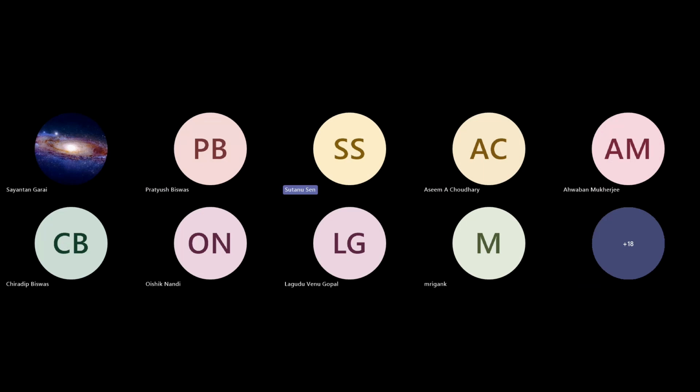We can assume we can give white noise in LTspice using the Spice noise model, but I have seen that it does not behave very well. So that is for noise analysis, you can do it. For transient noise, I don't think they have a model. So the noise analysis separately you can do, but in transient, I don't think you can.